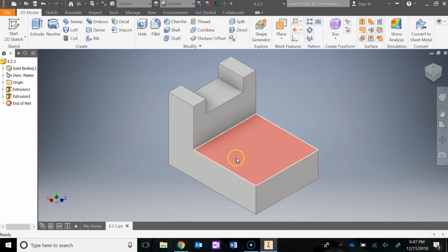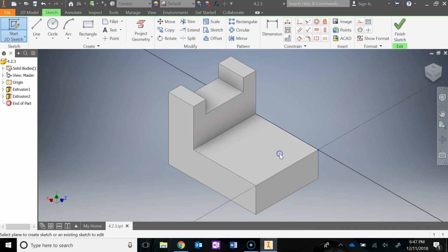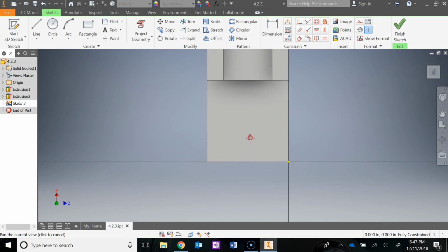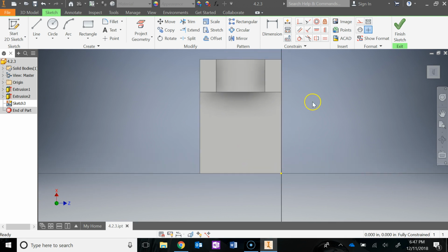1.5 by 0.5. So we're going to do a new sketch on this face. I'm going to turn this thing. I'm going to hit this little arrow. I kind of like it orientated this way a little bit better for me. Just preference there. And then I'm going to go rectangle again. Make sure you don't snap to the midpoint, just somewhere along this edge, so you should see a yellow dot. Left click once, move your mouse, and then we said the depth was 1.5, and then I'm going to tab to the other dimension, and the width was 0.5. Okay, so I'm done drawing the rectangle. Hit escape to get out of the rectangle tool.